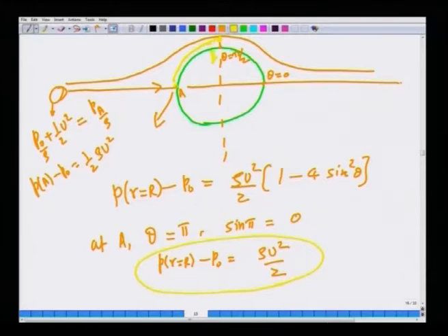This is point B, the pressure becomes the minimum. Now, if you follow from point B to point C, here the velocity is maximum, pressure is minimum, again it has to come to velocity minimum and pressure maximum. So, this region from B to C is a region of adverse pressure gradient, because the fluid is moving from a region of low pressure to high pressure.